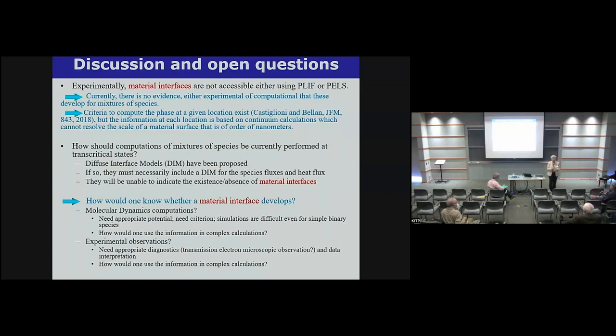Well, just like you said, I think that there is generally a, how shall I say, people get attached to what they know. And they know Kolmogorov, they know incompressible flows. But then when you go to compressible flows like that, the criteria and the ideas that Kolmogorov had are not necessarily applicable, because here the Kolmogorov scale is not the smallest scale.